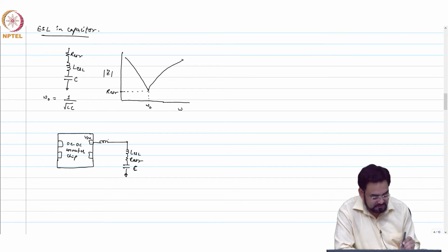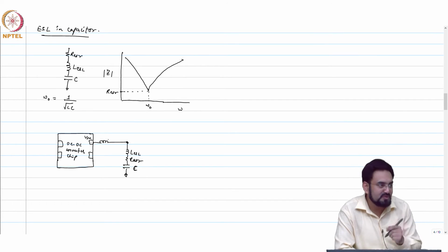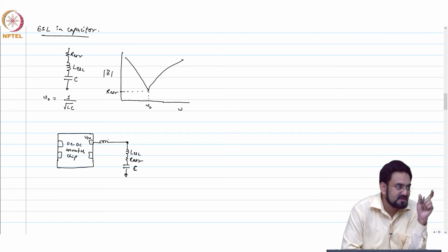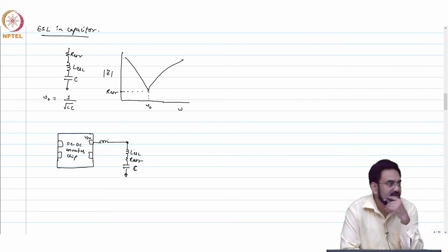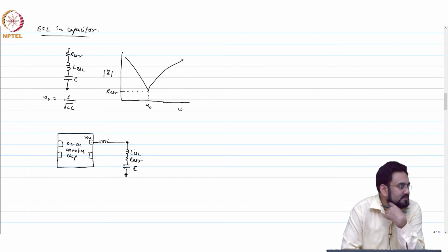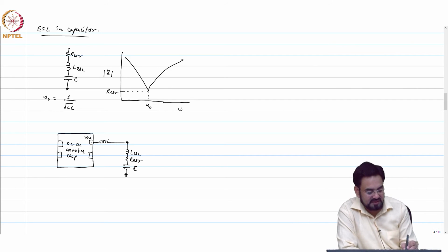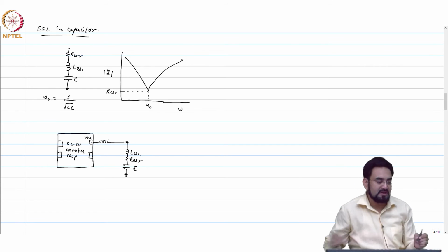So when you are connecting your capacitor to the inductor from the output, from the output to the capacitor end, when you are drawing the trace, you have to make sure that the trace length is minimized. Otherwise, that will also add some inductance, and it will be added to your LESL. Okay, so that's why you have to place the connection to the V out node carefully.